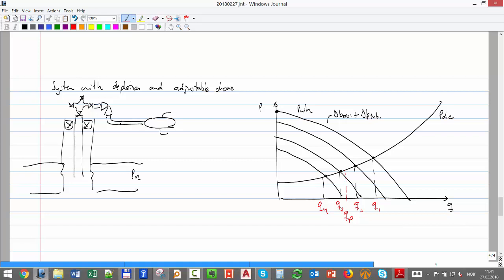In year, let's say here this is time 1, time 2, time 3, time 4. What do I have to do in time 1? I have to put a choke, right? Because if I put no choke, open choke, I will find this rate, right? The system itself will equalize. Equilibrium nature is like that. It will equalize in that rate. I want really to produce this rate here.